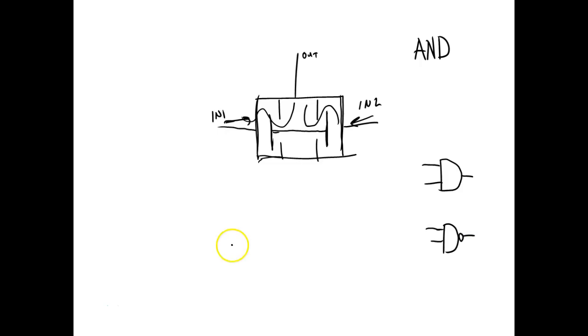So what would I do on this one? I would do exactly the same way to get a NAND. I'd come over and take this out, and I would run this into a normally open pilot operated valve.